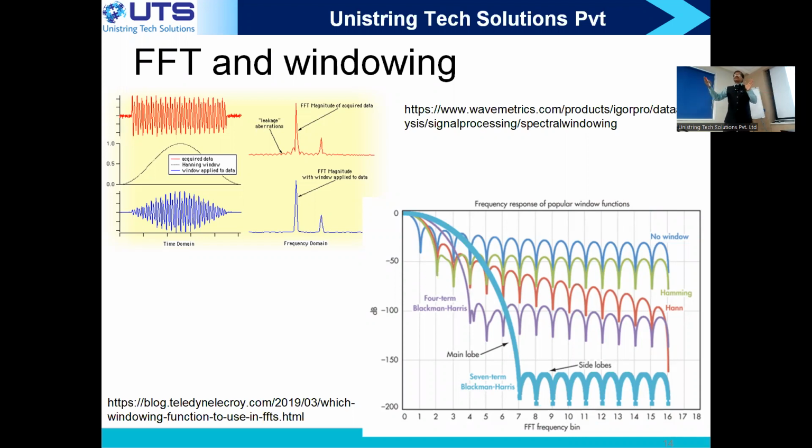See, what are you doing when you're doing FFT? Just go to the previous example. You have an ADC which is sampling at 1 microsecond. That's why you said the sampling rate is 1 megahertz, or the sample interval is 1 microsecond. So with 1 megahertz, that's why you said minus fs/2 to plus fs/2, minus 500 kilohertz to plus 500 kilohertz.